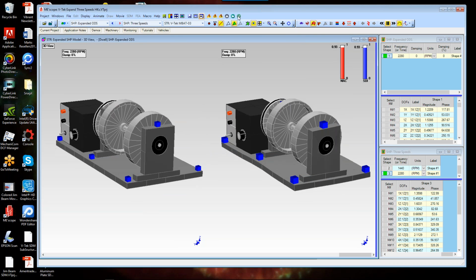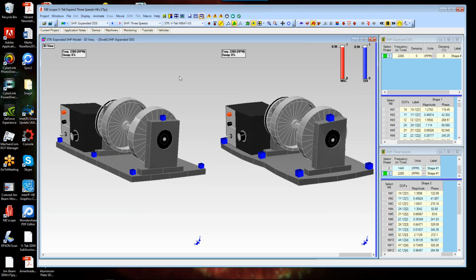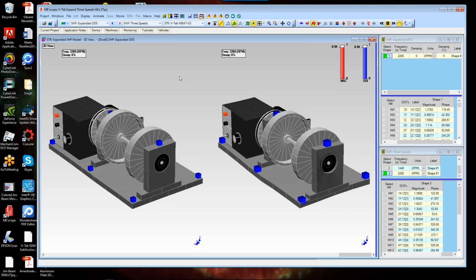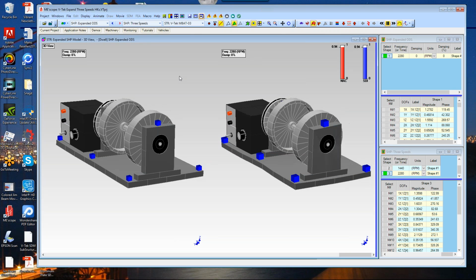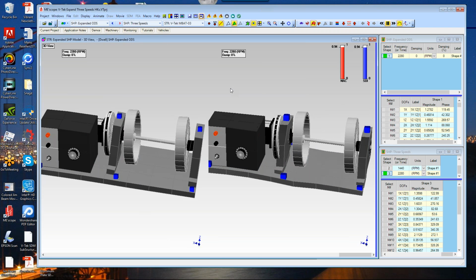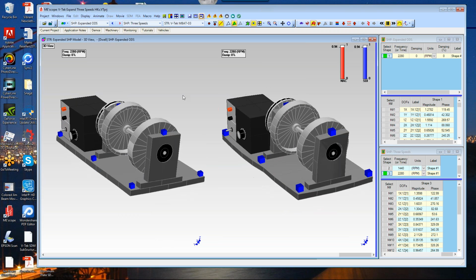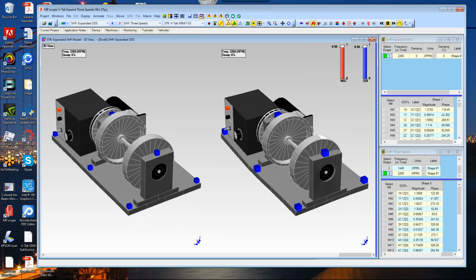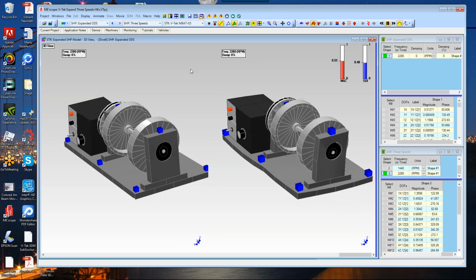And if I go to 10 modes, there might be a little bit of flex in here, and it goes to 94%. So those higher frequency modes, there's a little bit of flex. They're getting excited at 2280 hertz in this machine. So this is a nice way to see how modes participate in operating data.